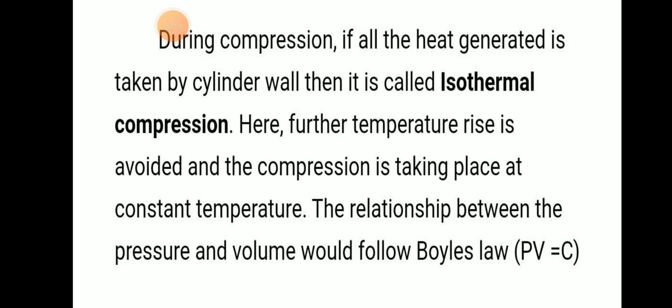During compression, if all the heat generated is taken by the cylinder wall, then it is called isothermal compression. Here, further temperature rise is avoided and the compression takes place at constant temperature. The relation between pressure and volume can be found by Boyle's law, that means PV is equal to a constant.